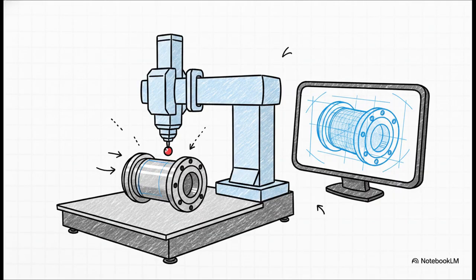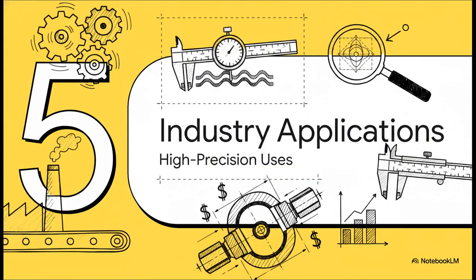Now, obviously, in modern manufacturing environments, we aren't always relying on a machinist meticulously hand-cranking a dial indicator. A lot of this process is heavily automated now. We use coordinate measuring machines, CMMs, and incredibly intelligent model-based metrology software like Verisurf, for example. These systems can literally just import the 3D CAD file with all the GD&T data already baked in. The software recognizes these complex simultaneous requirements, figures out the datums, and runs the inspection digitally, which pretty much eliminates those human calculation errors.